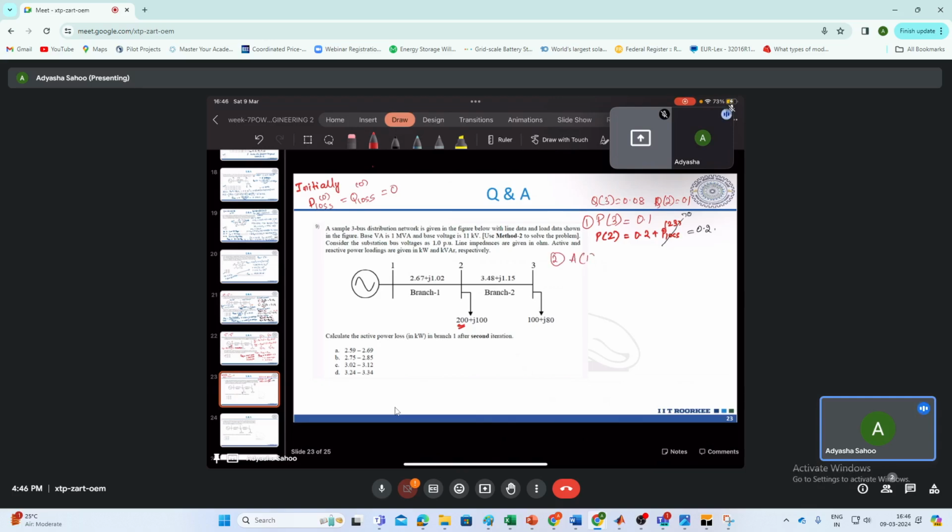So A for branch 1, branch 2, so that was P2R1 plus Q2X1 minus 0.5 V1 square, and similarly D1 you can calculate here as A1 square minus R1 square plus X1 square into P2 square plus Q2 square, whole square root. And what about A2 and D2?